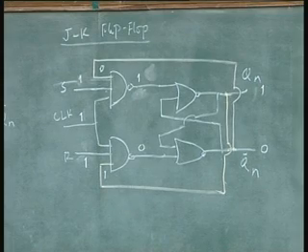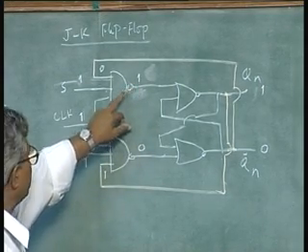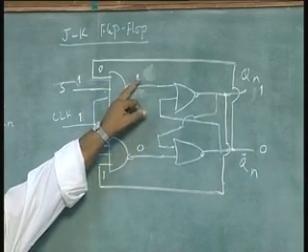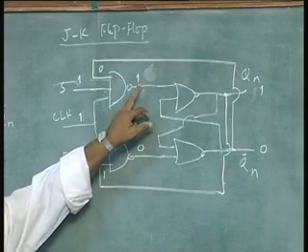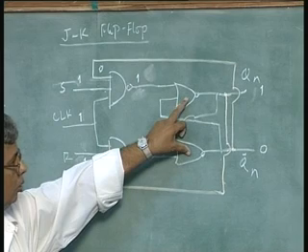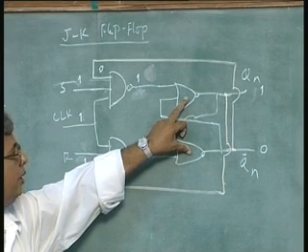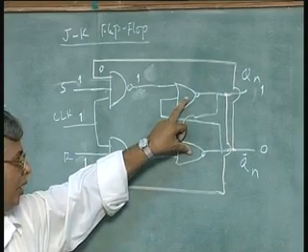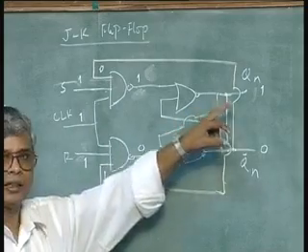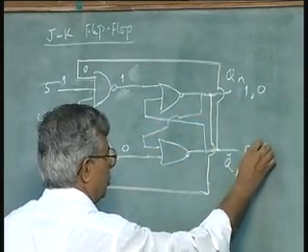So, this condition is going to be the condition by which, because of the inverse of the NAND gate, this becomes a reset condition. Earlier we saw this 2 input NOR gate connected back to back as an RS flip flop. Remember that RS latch, that means R is equal to 1, S is equal to 0, made a reset condition. That means it is going to become 0 output and 1 output.